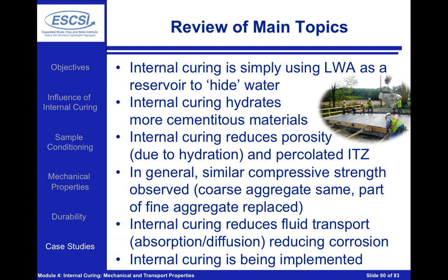In general, we see very similar compressive strength. The coarse aggregate has remained the same. Most of the rest of the system has remained the same. The only real difference here is we've replaced a portion of the sand with lightweight aggregate sand. The idea here is that we're also hydrating more of the paste, so we typically see a slight increase in the strength of the paste, resulting in a very similar compressive strength of our concrete.